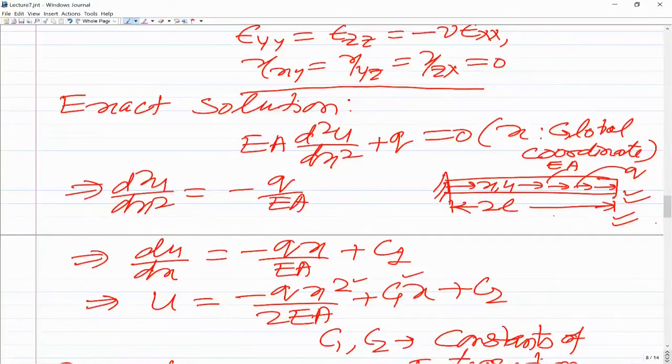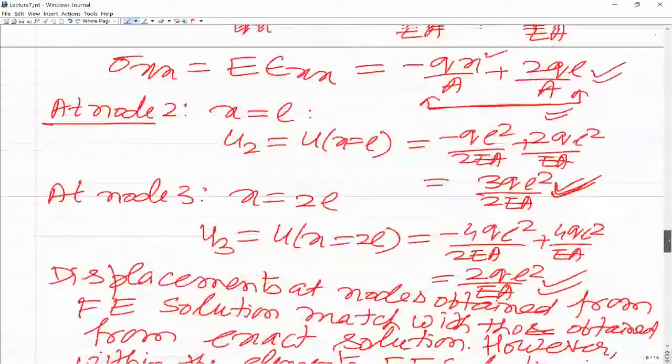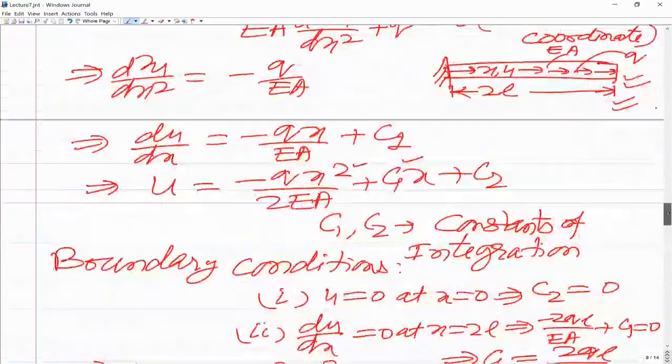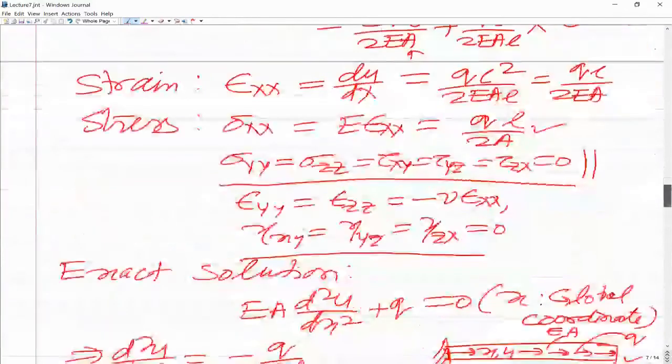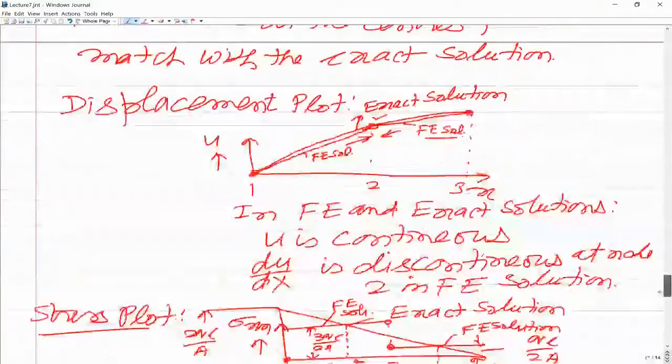So first you will solve the second equation for u2, then the first equation you will solve for q11, and then the third equation you will solve for q22. So with the same assembled system you can solve different types of problems with different boundary conditions.